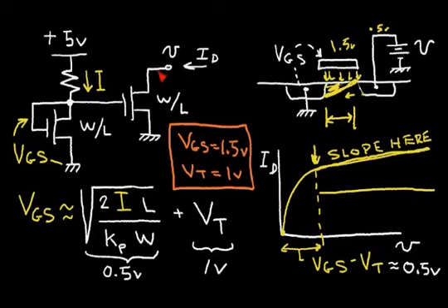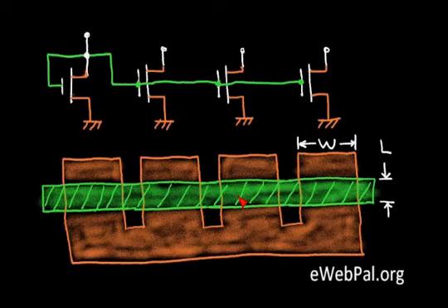So now let's look at how we would do the layout of this particular set of CMOS transistors. This shows a typical layout for this current source. Now here I've added 2 additional N-channel transistors. So this part is our original current source that we examined previously. Now below I've shown the layout, and I've kind of color coded this.